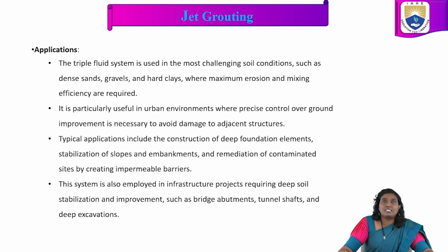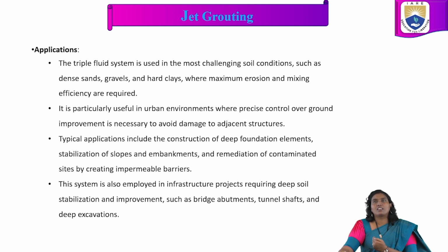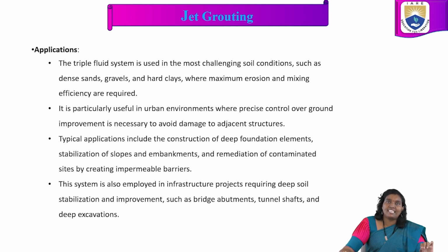The triple fluid system is used in the most challenging soil conditions such as dense sands, gravels and hard clays where maximum erosion and mixing efficiency are required. So whenever maximum erosion and mixing efficiency are required, we are going to choose this triple fluid system. These are the most challenging conditions we are going to face in the triple fluid system of jet grouting.